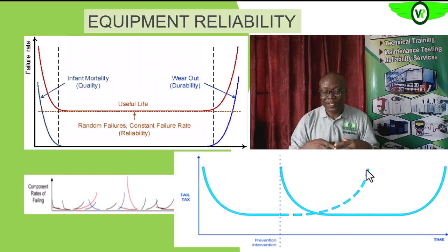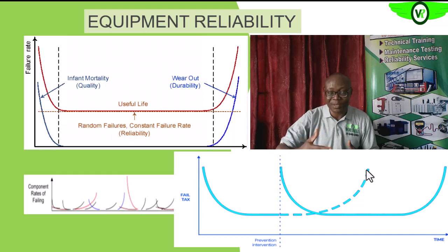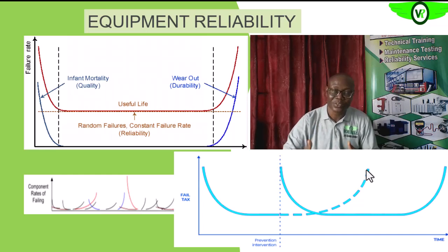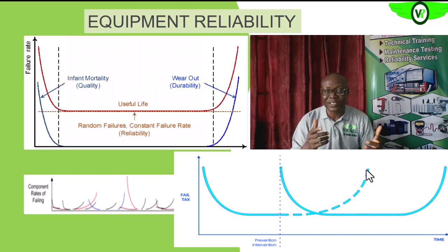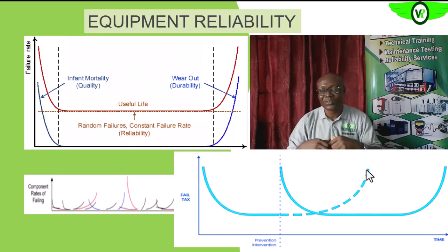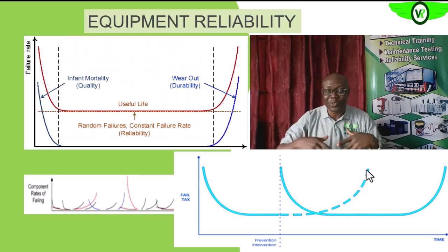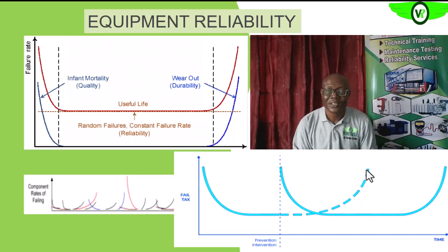manufacturers, usually when you buy equipment from them, they design a maintenance program that comes with it, like a suggestion to you, the kind of maintenance that you carry out, the time interval when you start using the equipment, the amount of time it will take for you to do some change outs on those equipment, the amount of time it will take for you to do oil change outs, bearing change outs, and do some checks, also maintenance checks. Okay,